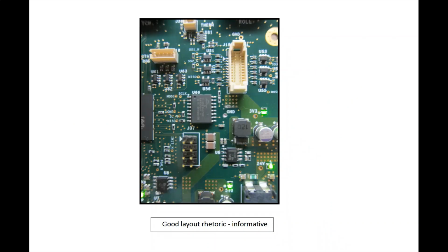Now, we can apply rhetoric to layout, and it has the same objective as it does in the schematic. Namely, that is clarity in presentation. And we can see that this layout exhibits it. The connectors have been labeled with their reference designators. They all have pin 1 called out somehow. And the ref-des is as close to pin 1 as is practicable. The connector functions are also indicated in the printed text.